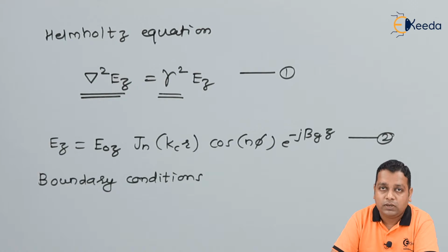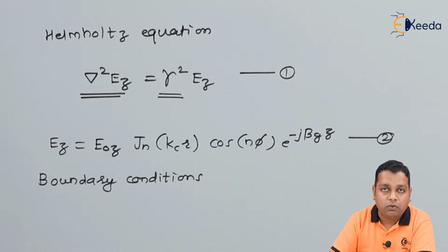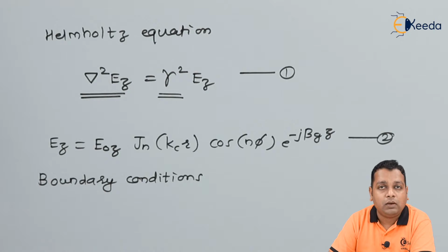Hence the application of boundary conditions is very important. Ideally we don't want any electromagnetic wave to penetrate the perfect conductive material. Practically there may be a certain depth to which it extends, which we can determine with the help of the skin depth, but it will be very small, so it allows internal reflection.